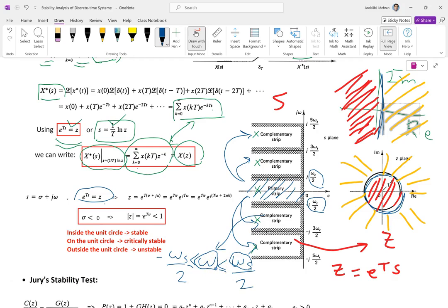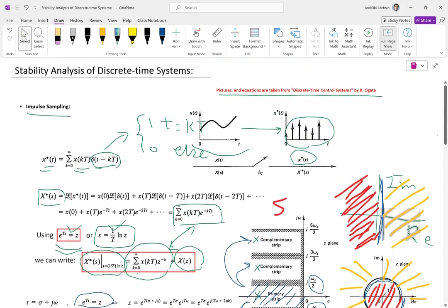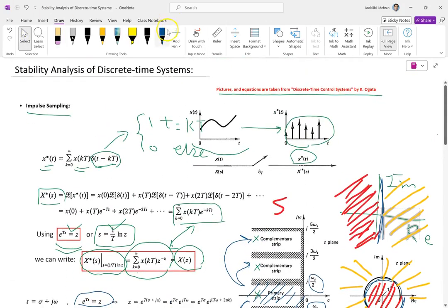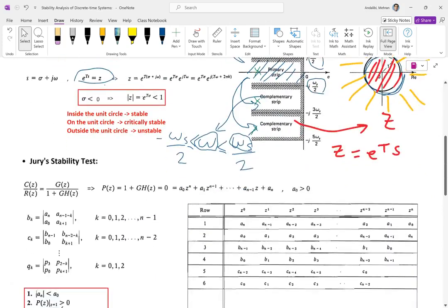And if that's the case, then you can always reconstruct what? You can reconstruct the analog signal from the digital signal back, okay? So if you want to go back later with a D to A, you can do it as long as you are inside that primary strip, okay? And there will be no problem in the system.